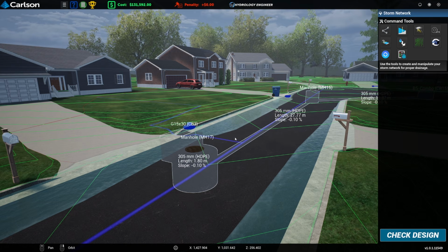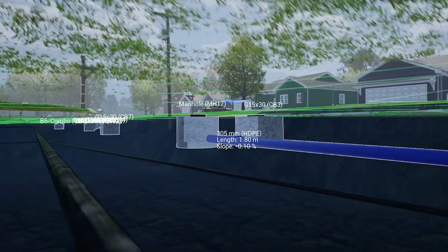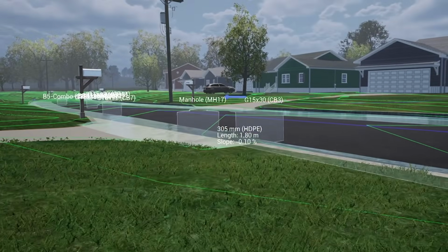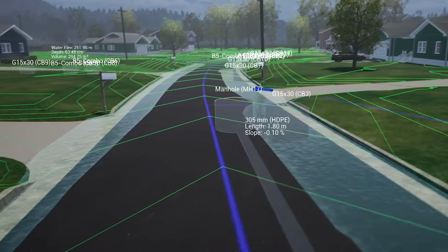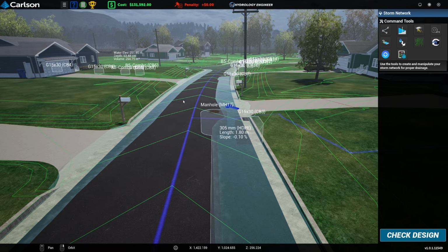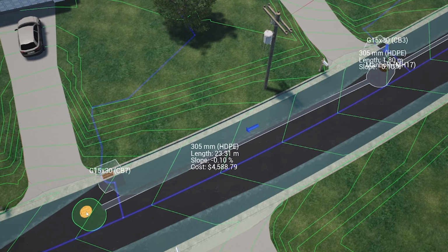So now you can see our pipe network goes completely parallel with the road. You can see it going downhill. And it looks like our mains water is under the verge. Can you see it's under this bit of grass? It's not actually under the road. So by putting ours in the road, we're well out the way of that. So that's pretty good. We'll shove another manhole so that gully can connect.